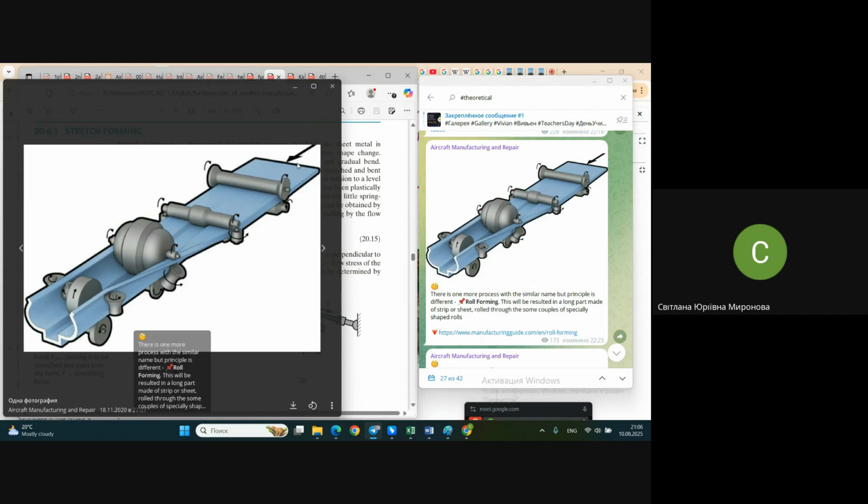Look, the flat sheet or flat strip of the sheet passes through some pairs of rollers, and the rollers are created in such a way that, step by step, continuously of course, they change the cross section of the strip with the minimum possible stresses, in order not to break it, not to tear something off on the way, not to create the maximum of deformation, these ultimate deformations inside.